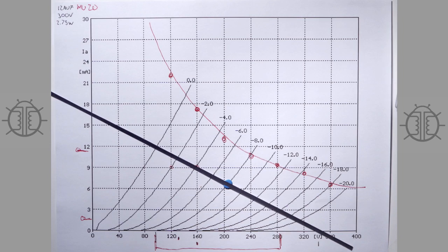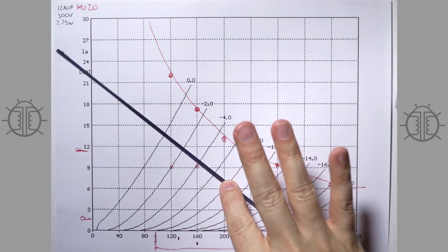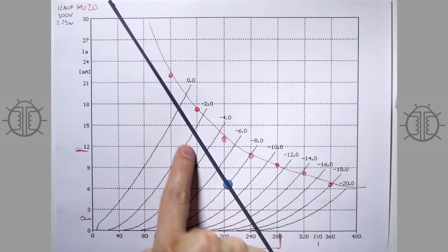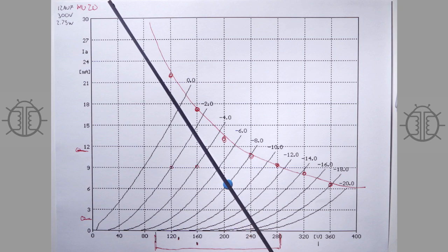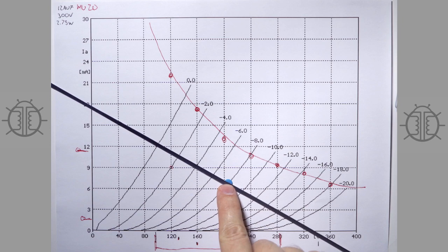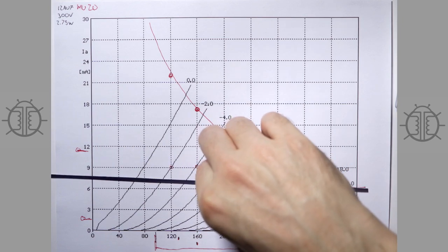So you can see now how the gain changes with the loading, and the more you load it, your voltage gain goes away. But now all of a sudden you're swinging through lots of current. But you're also getting into a very nonlinear part of the tube where it swings up a ton and swings down and gets all squishy down here. That's not a technical term. Anyway, so that's the mu, or the intrinsic gain of the tube.